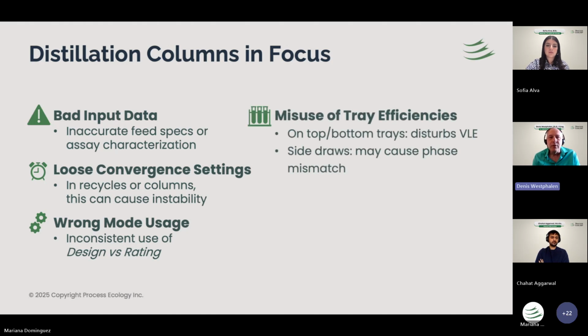Let's talk a little bit about the tray efficiency. A few pieces of advice here. First, be careful with your top and bottom trays, your overhead and your bottom. Our advice is do not mess with those trays. If you use the Murphree tray efficiency, where you input a fractional number, don't touch those trays, because typically they cause issues in your simulation because of the way that the algorithms were implemented.